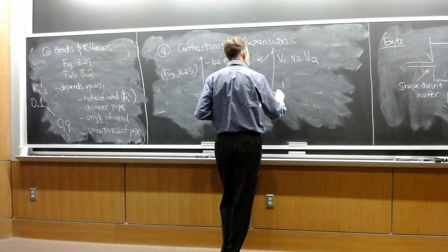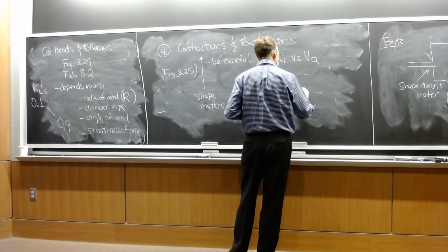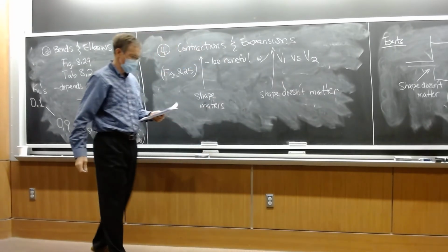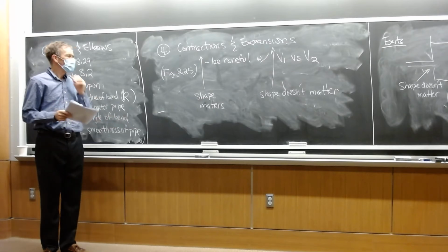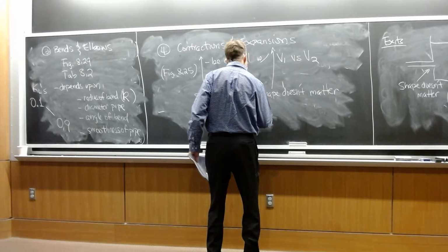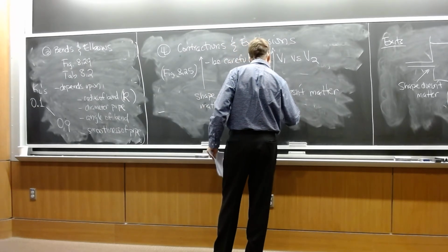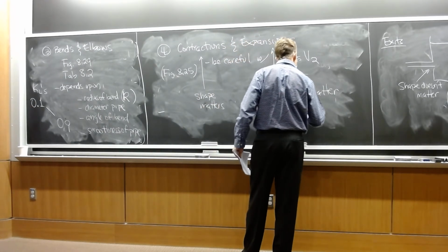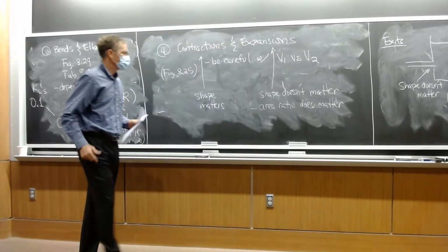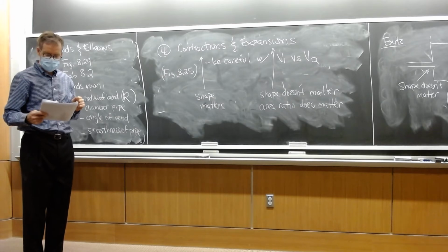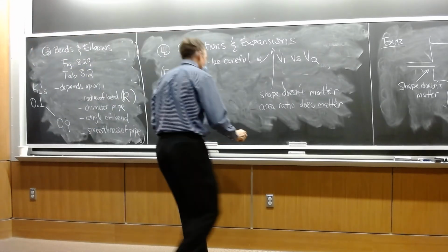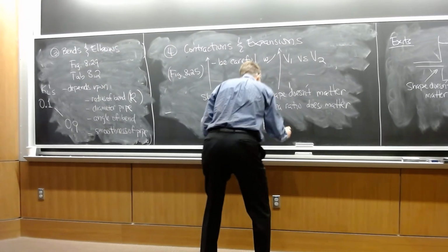It doesn't so much matter on the expansion shape, but what does matter is that there's an area ratio that you can calculate from A1 to A2. And there is an equation for the K of L that's a function of that.